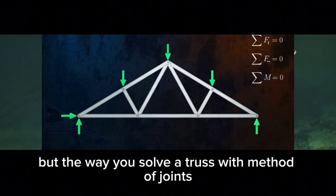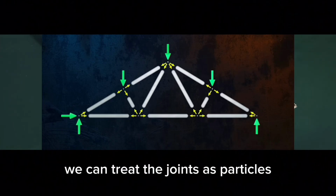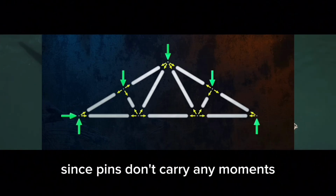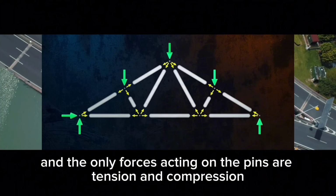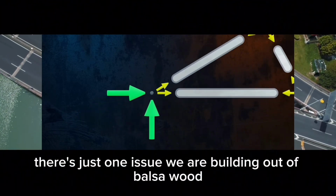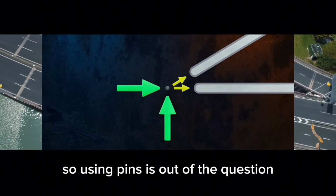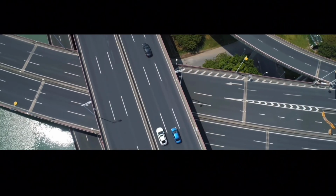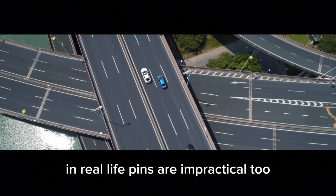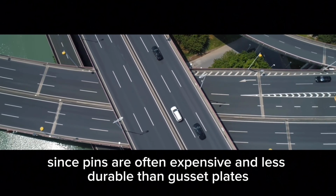But the way you solve a truss with method of joints is that even though the truss is a rigid body and not a particle, we can treat the joints as particles, since pins don't carry any moments, and the only forces acting on the pins are tension and compression. There's just one issue. We are building out of balsa wood, so using pins is out of the question, so to hold our members in place, we'll use gusset plates. In real life, pins are impractical too, since pins are often expensive and less durable than gusset plates.